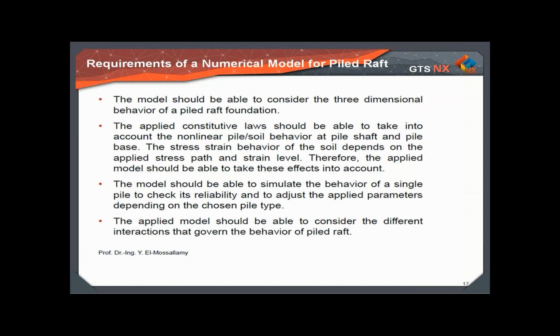The applied constitutive laws should be able to take into account the nonlinear pile-soil behavior at the Piled-Raft and pile base, and the stress-strain behavior of the soil depends on the applied stress path and strain level. Therefore, the applied model should be able to take these effects into account as well.